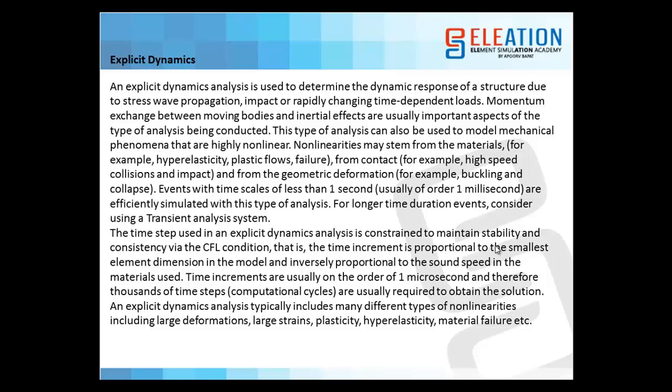If my roll cage is impacting on the engine mounts, transmission systems, knuckle, hub or tie rod, how these contacts are happening you can also predict in dynamic analysis. And from geometric deformation, for example buckling and collapse, the prediction of buckling or collapse, or deformation with respect to time, can be easily captured